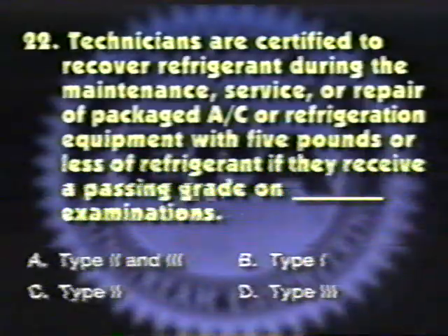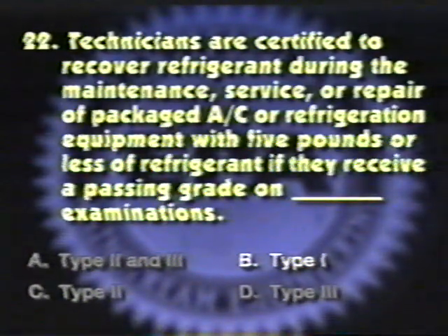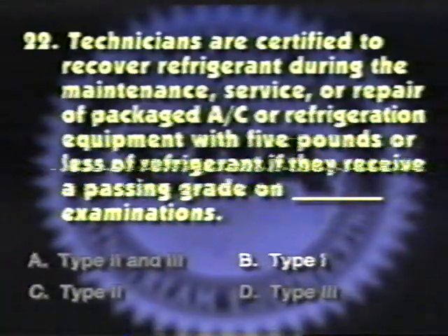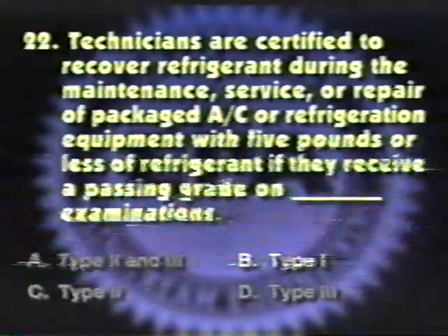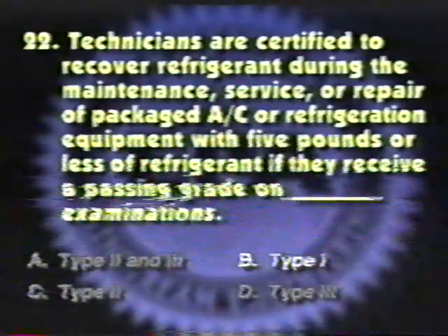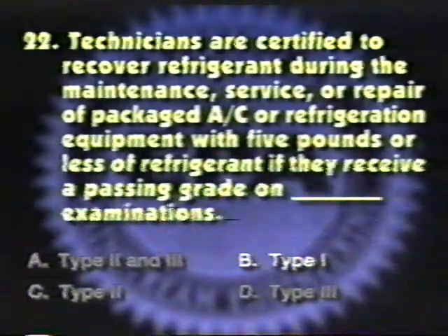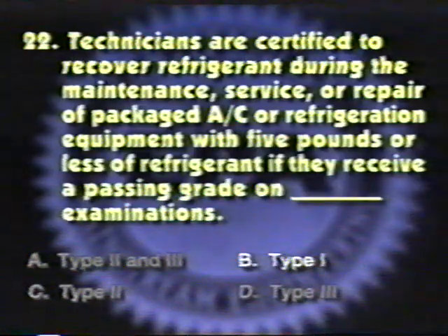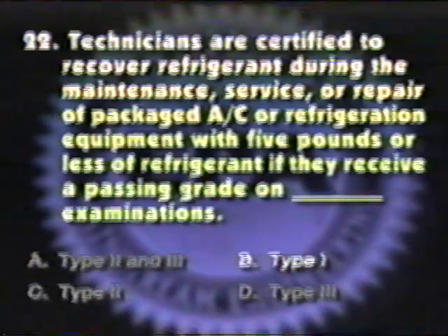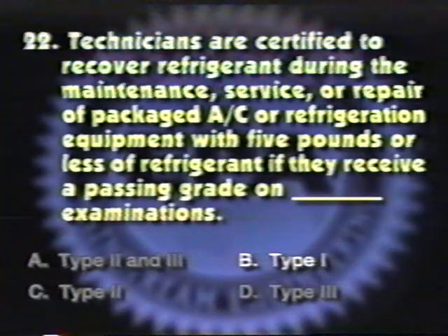The correct answer is B. Technicians receiving a Type 1 small appliance certification can recover refrigerant during the maintenance, service, or repair of packaged AC or refrigeration equipment with 5 pounds or less of refrigerant. Only Type 1 or Universal Certified Technicians can recover refrigerant from these units.